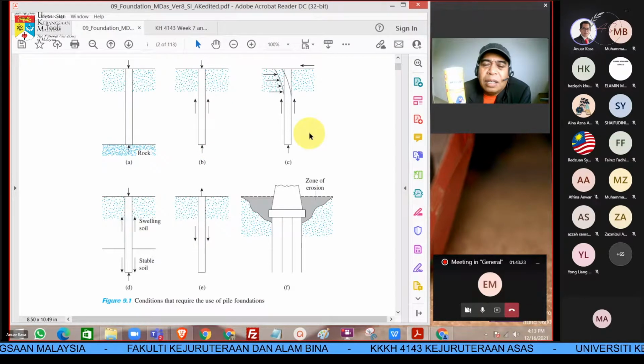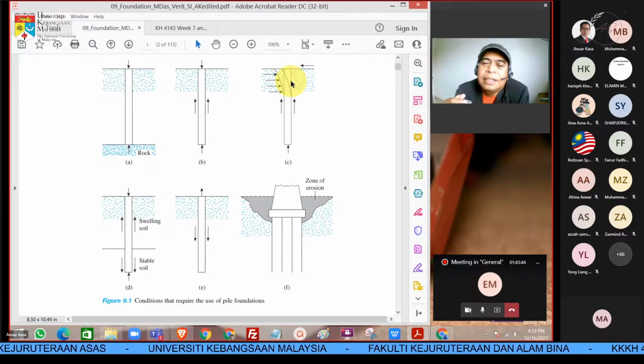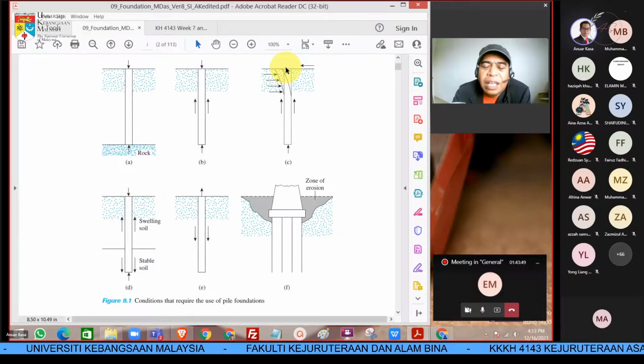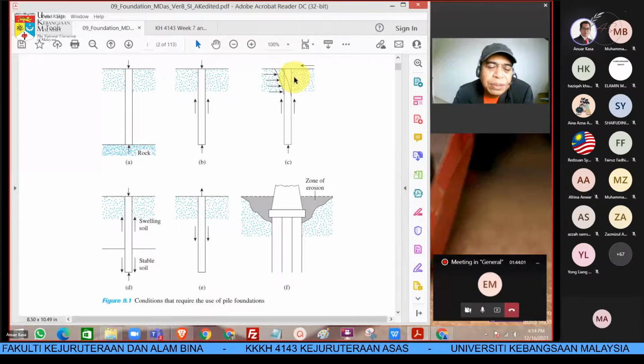And for the third one, it is to support the lateral or horizontal forces. If there is a horizontal force, we can take care of that lateral force by having a pile. This also takes care of the vertical force. Let's say we have a vertical and horizontal force. So we can cater to the horizontal force by having a pile, which will take the moment. Yeah, those are the three.